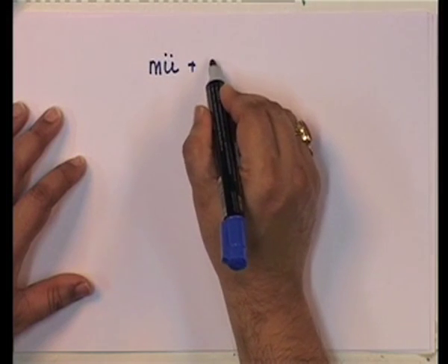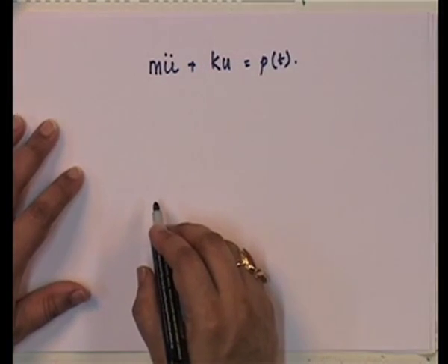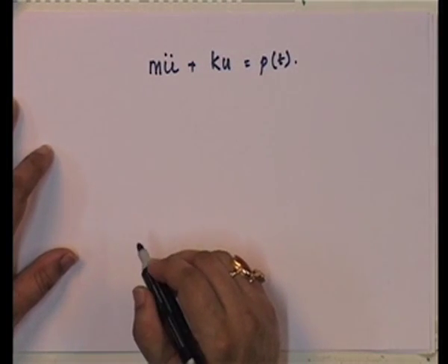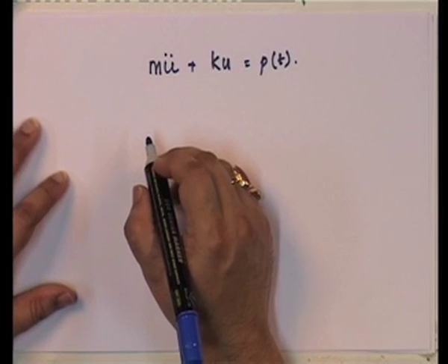Now let us look at how to solve. Since T r is very small, I am going to still continue to solve the undamped system, because understand that since T r is much less than T, and even in phase 2 the peak will occur somewhere in the beginning. So, for all practical purposes damping does not come into the picture, and so I shall only continue to solve this problem, because I am looking at pulse load response characteristics, and that is why, to highlight that, I will continue with the same thing.